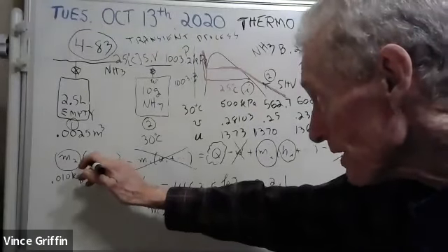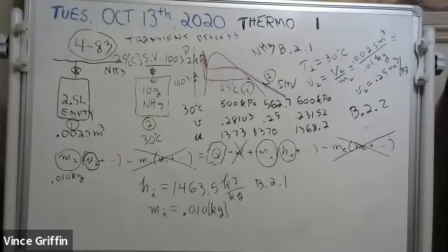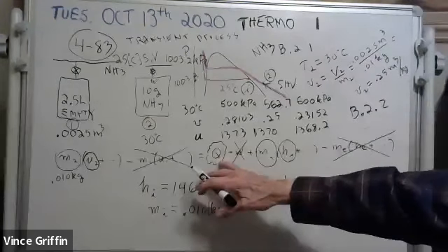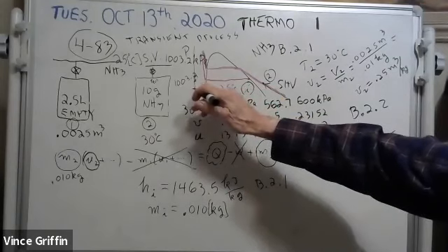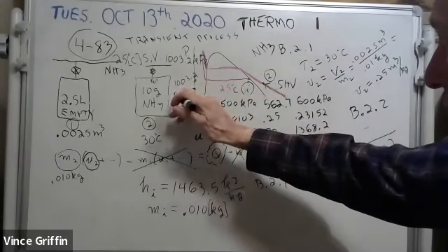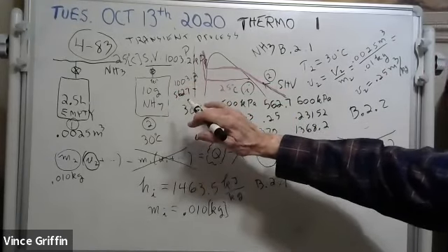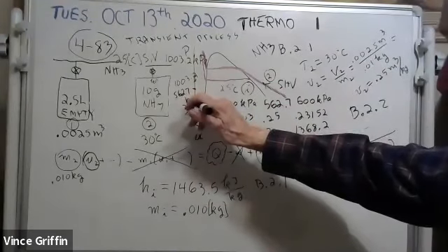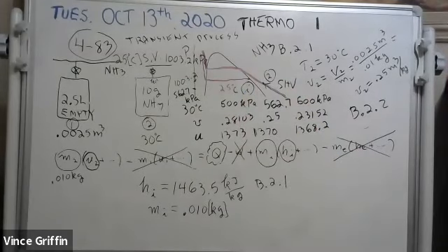This is our first law of thermodynamics that we just figured out, U2. We got everything we need now. I just need to write in the numbers. And we're going to solve for, oh, by the way, here's our pressure at 2. See it? It's 562.7. Remember, I told you it's going to be less than 1,003. And now we know what the final pressure is. It was 0 to start with, and now it's 562.7.